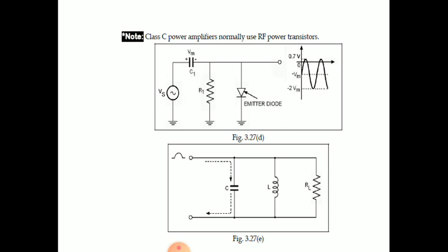The capacitor charges to the maximum and starts discharging, reaches zero. The same current will flow through the inductor in the negative direction and reaches the negative maximum, and again reaches zero, and again the capacitor starts charging and reaches maximum, then zero, and again negative and zero. So there will be production of a smooth sine wave.